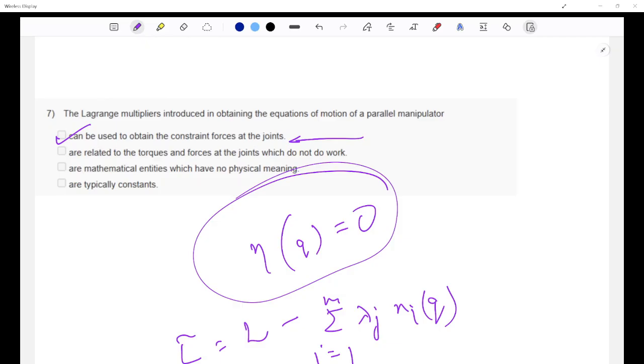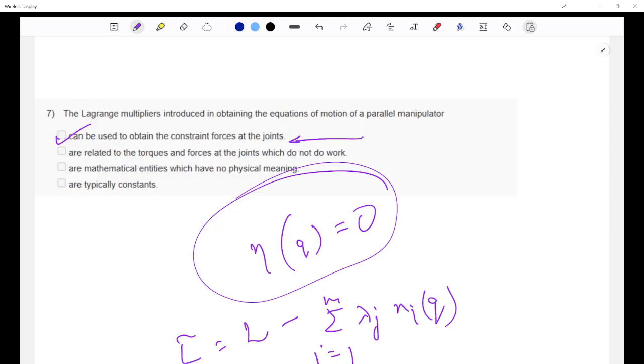The reason is the motion of the system always satisfies the double differentiation of the constraint equations. So the constraint forces do zero work, and this is the fundamental property of ideal constraints. So this is also correct. For example, if there is a hinge joint, the hinge reaction force prevents motion in a certain direction but does not produce any work.